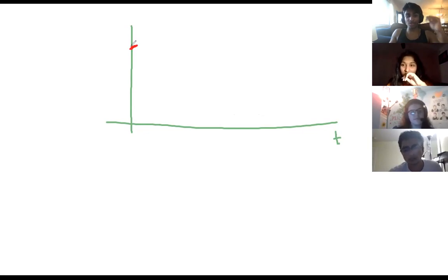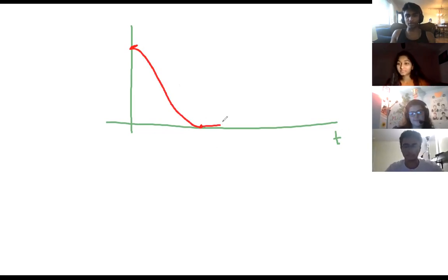So you close the switch, current can flow. That means that between these 2 points, there's no potential difference. It's the same voltage, so it becomes very low. But that doesn't happen instantaneously. In a perfect world, yes, but in the real world, it'll slowly hit very low and then hover at this value. And then let's say you turn off the switch, it'll go back up after some time. So this is voltage.